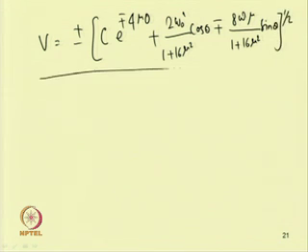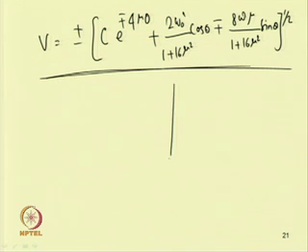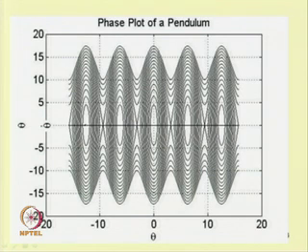So one can plot this equation for v and theta, where v equal to d theta by dt, and one can find the response of the system. If one recalls, in case of conservative systems without considering damping, the potential well has been plotted and one can obtain stable nodes at these points, where periodic responses are obtained, and one has saddle points also in between.